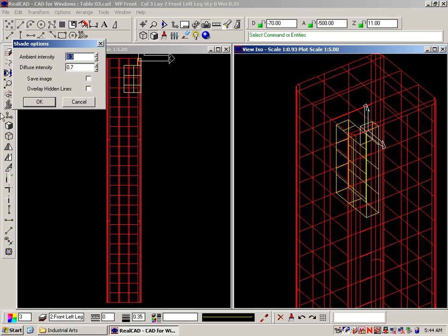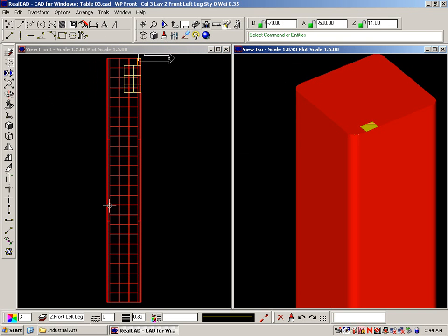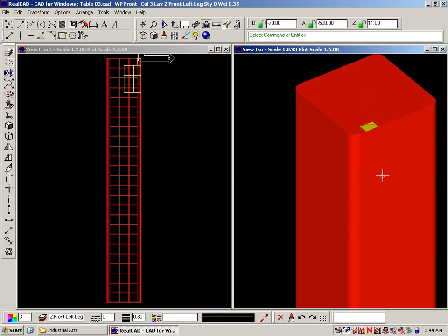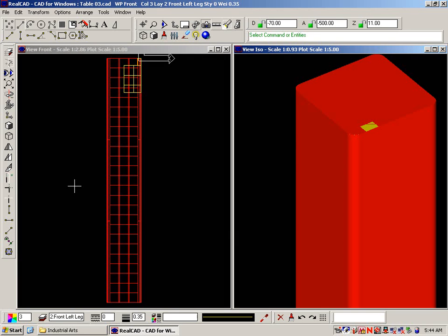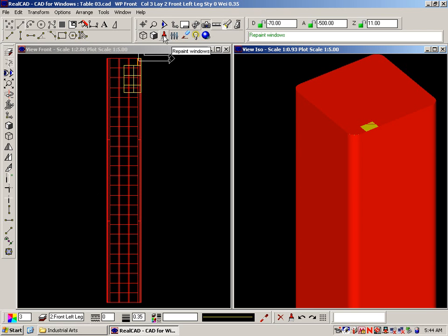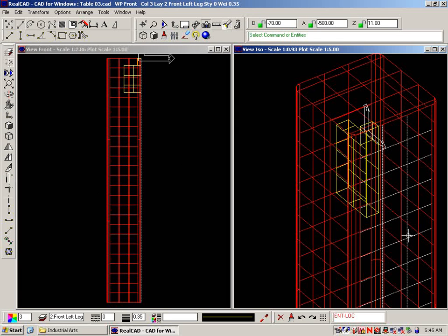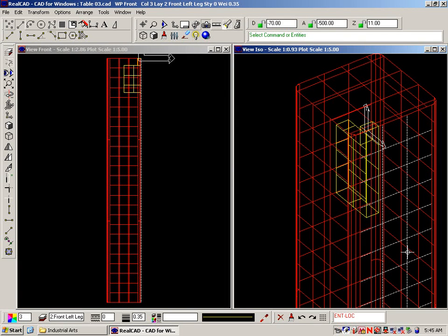When we shaded that right hand view in the last tutorial, you see there wasn't actually a hole there. So we have surfaces we need to modify, and the only way we can modify surfaces is to first delete them and then replace them. So the front surface here, or the right hand surface, needs to be deleted.